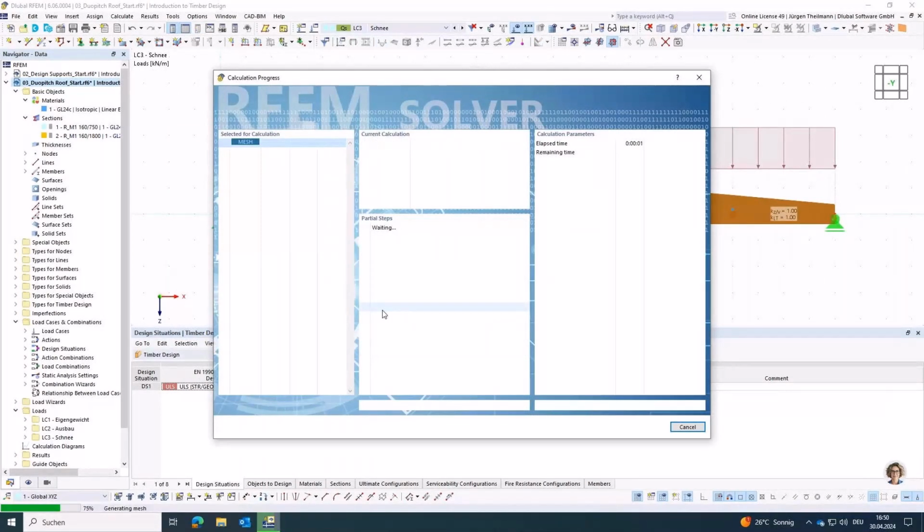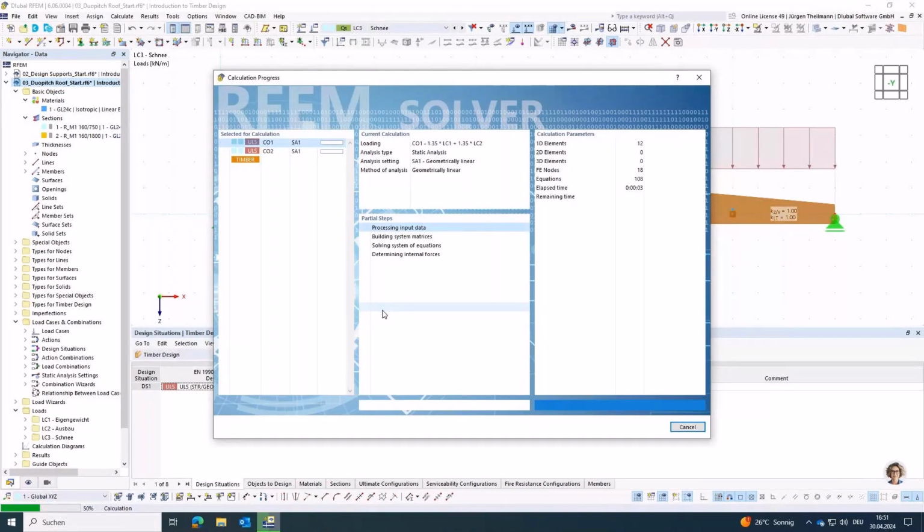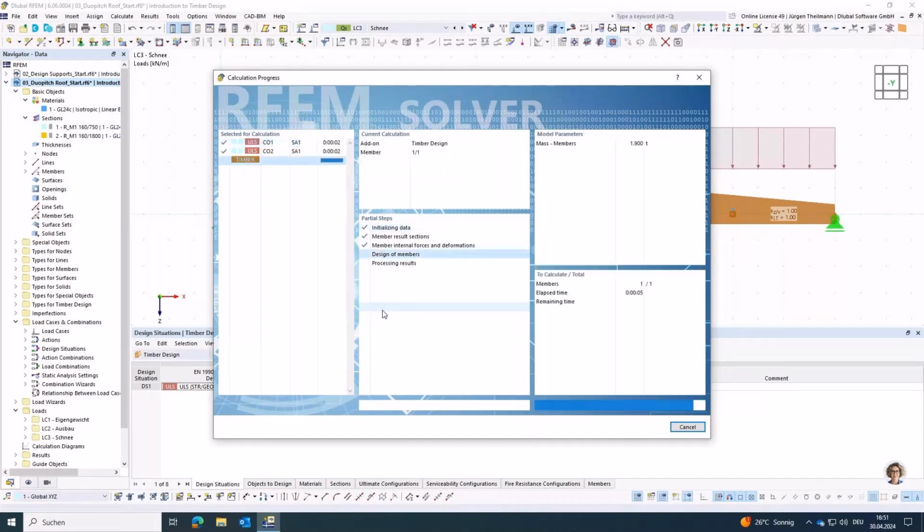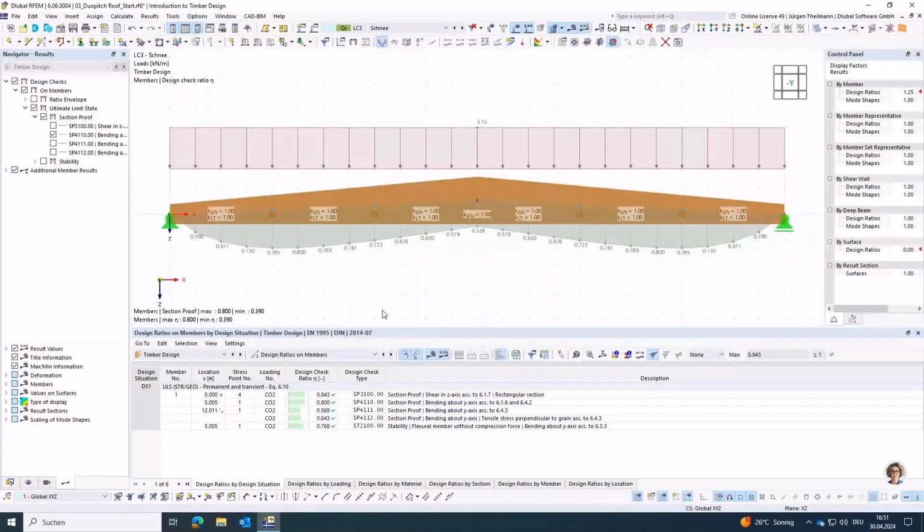Yeah, and this is basically the same idea you also got from the training introduction to FE analysis, where you basically always say that you need to keep the mesh as coarse as possible, but at the same time as fine as necessary. Otherwise, you would have a maximum of the bending stress at this intermediate node, when in reality it's a bit more to the inside of the member.